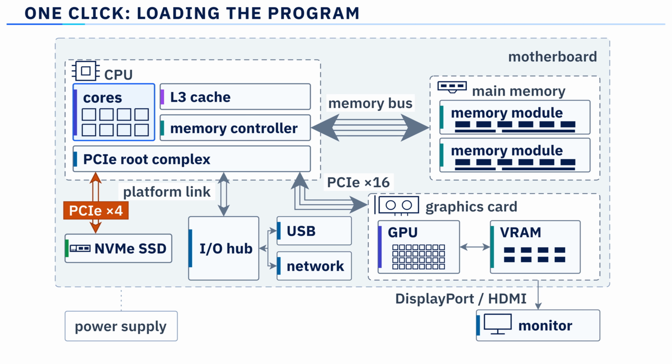The controller sends the data back over the same lanes and places it in main memory itself. No core copies the bytes. That is direct memory access. The device writes memory, and the core stays free to do other work.